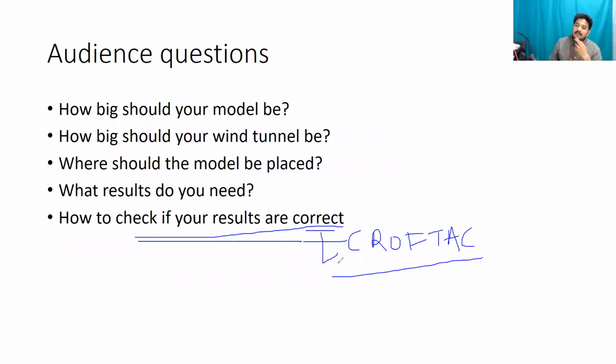What actual validation is? That's a great question. So what you can do is, for example, if you take an airfoil, right? There's a parameter called angle of attack, which basically says how the airfoil is tilted. And say that you have the lift coefficient. The lift coefficient is going to increase, and then after some time, it's going to stall, right? This is a very classic behavior, fundamentals of aerodynamics. Now, for some airfoils, experiments have been done, and this curve has been obtained realistically, meaning from pressure sensors and all the things that you guys are talking about.